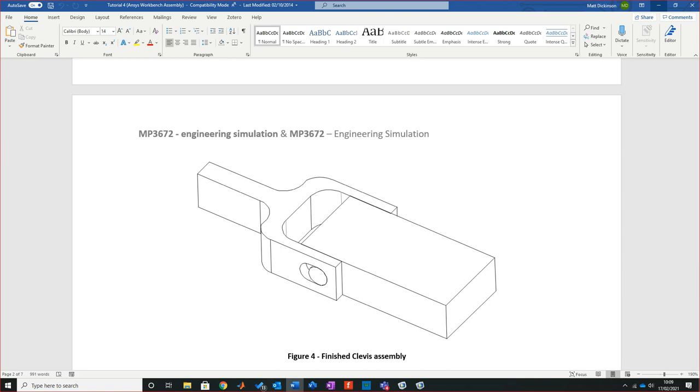You'd instantly expect that. Now, given that there's radii to the back of the arms as well, you're going to expect high force there, high concentrated stress as well. The other thing when you look at that is the first interface where the pin sits.